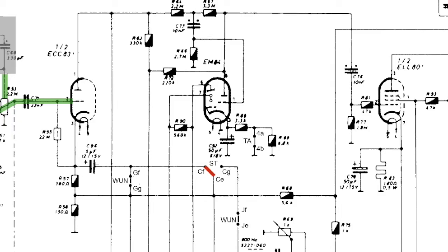This capacitor is connected to the cathode, but it's also connected to one of the tonal select switches. We'll ignore that. It goes across here through that switch to ground. So this capacitor basically bypasses that resistor. So this is our cathode resistor with a bypass, okay? Now, again, if we look at this triode, if you have a signal coming in, if this triode has B+ on here, it'll actually amplify.